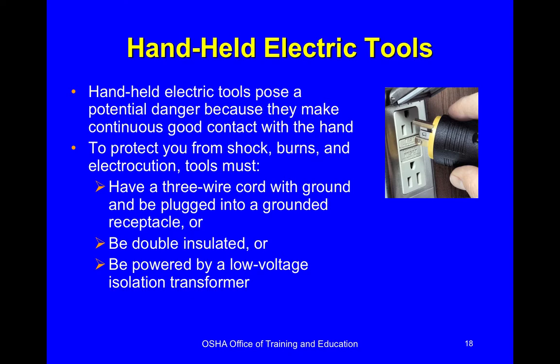Handheld power tools. Again, I already said you're holding it in your hand. Okay, you've got a really good chance, if there is a problem, of getting a severe burn or actually hanging on to it. You can't let go of it. And now you've increased the duration that you're in contact with that circuit. Okay, so handheld power tools will either be double insulated or they're going to have a three-prong plug.